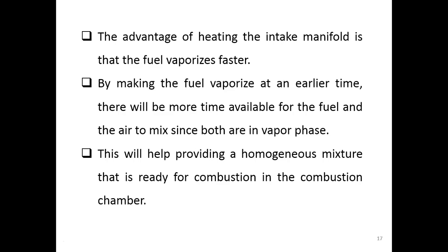So as we mentioned, heat helps the fuel to vaporize faster. And since it vaporizes faster, there is more time for the air and fuel to mix together. So it helps provide a homogeneous mixture. This homogeneous mixture will be ready for combustion in the combustion chambers.